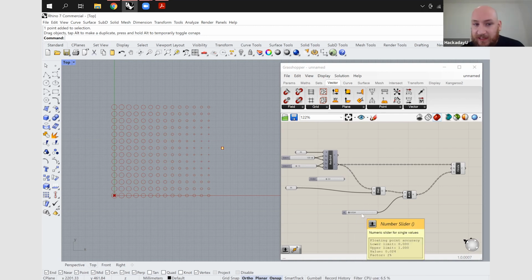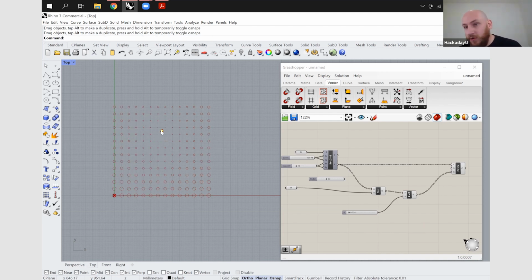And you basically can have multiple attraction points within your model. You could also, if you guys want to try it out, do a curve and do the distance between the curve, the nearest point, sorry, the distance between the curve and the center point of each of those circles. And then it's an attractor line where you're doing the sort of same model.